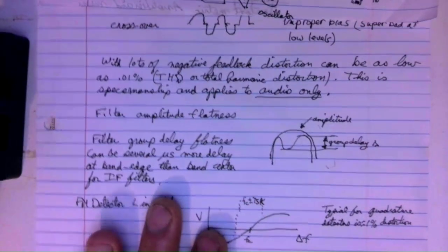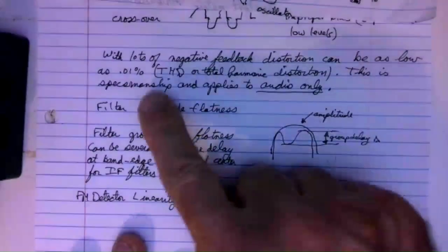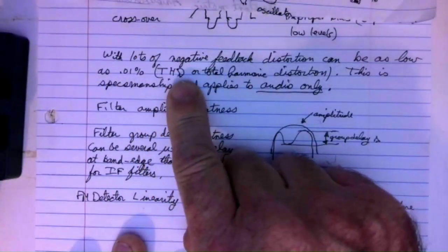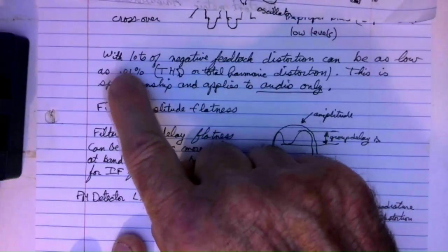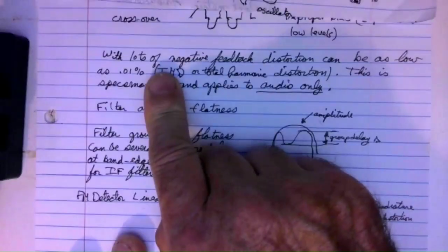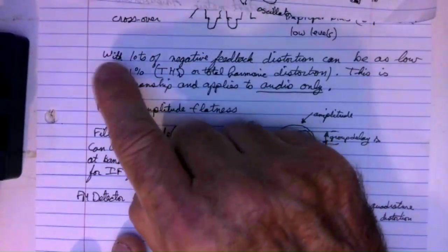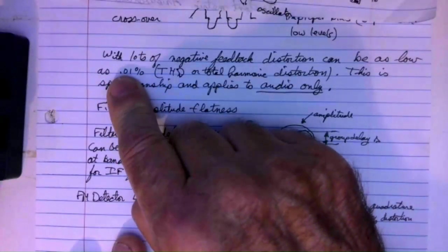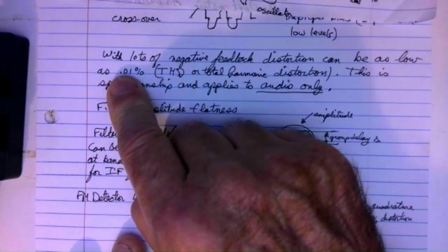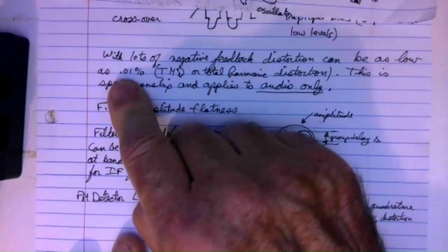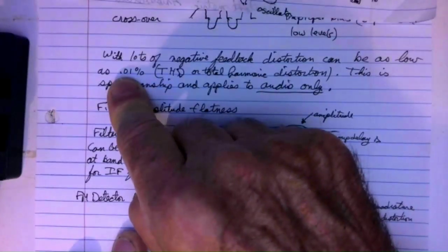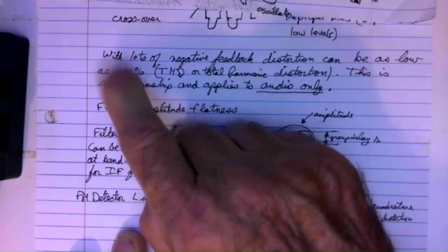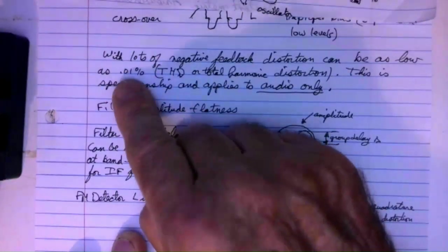It's not a realistic number, nor do you need it, and it may do more harm than good. Some people, for instance, prefer vacuum tube receivers that would have distortions of several percent, 2, 3, 4, 5% distortion, and they would prefer the audio quality from a vacuum tube audio amp over a bipolar amp that might have this kind of distortion, just to give you an idea.